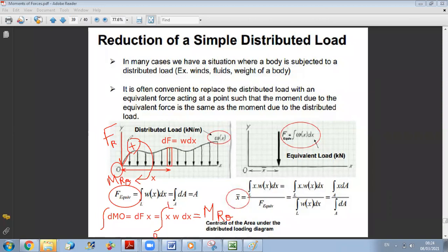How should I displace it first, in positive x or negative x? Positive x, because to produce a clockwise moment, I should move my force in positive x. Now, what should be the distance to move it in order to get an equivalent system? The moment produced by this force should be equal to the resulting moment MRO. So what is the equation I can write?